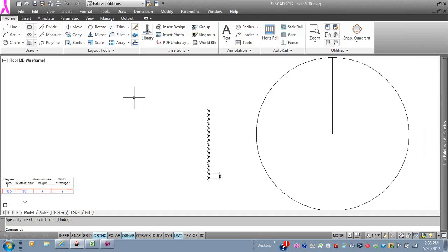Getting some feedback here. All right, now I'm going to do a rotate command, and I'm going to set up the ending line. So I'm going to rotate this line over, but I'll specify the base point, which is the end point. At the bottom, you see it says copy and reference. I'm going to use both of those.